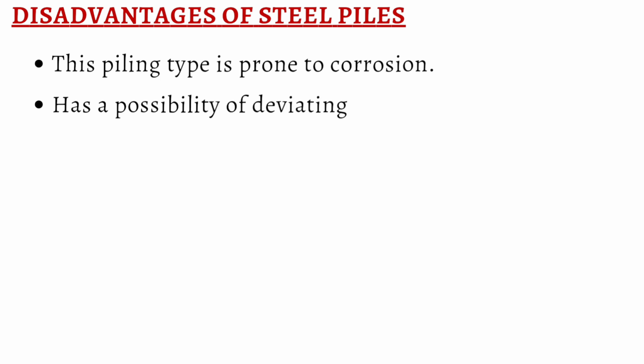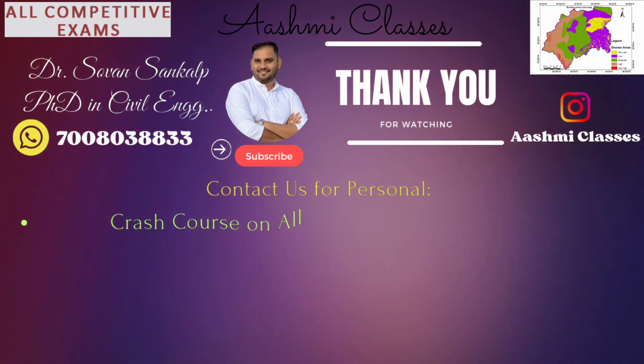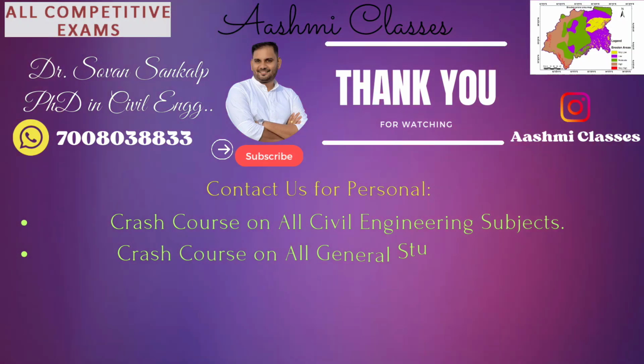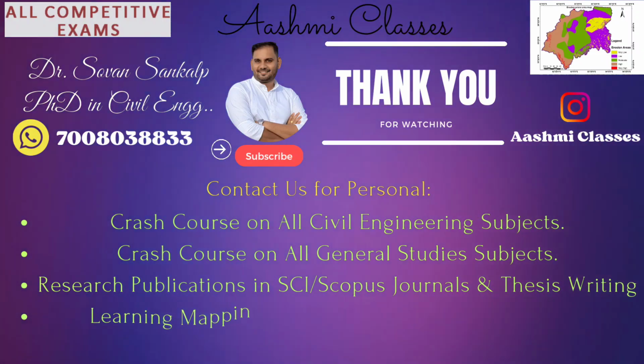Steel piles. Steel piles may be of I section or hollow pipe. They are filled with concrete. The size may vary from 10 inches to 24 inches in diameter, and the thickness is usually 3/4 inches. Because of the small sectional area, the piles are easy to drive. They are mostly used as end bearing piles.